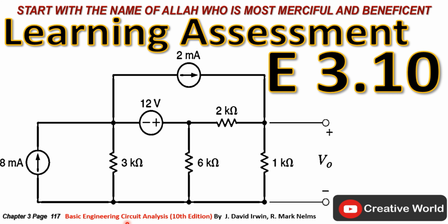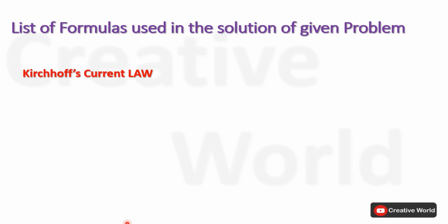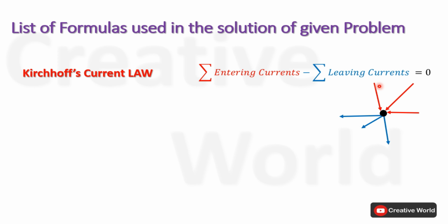E3.10. While solving this problem, we will be using Kirchhoff's current law. According to this law, a cumulative current on a node inside an electrical network is always equal to 0. Sum of all entering currents on a node is always equal to sum of all leaving currents from that node.